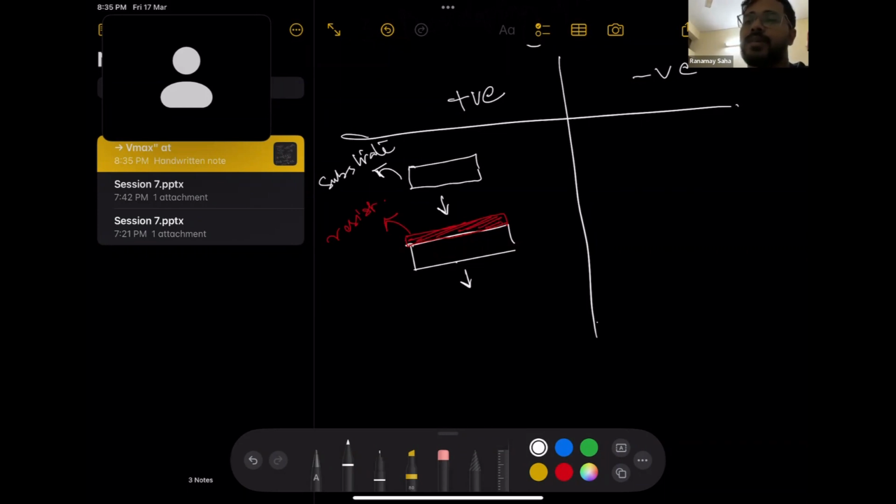So now what you do is the patterning. Okay, actually to improve the bonding you can sometimes coat an adhesion promoter layer before putting your resist. Okay? That actually improves the bonding of your resist and substrate.